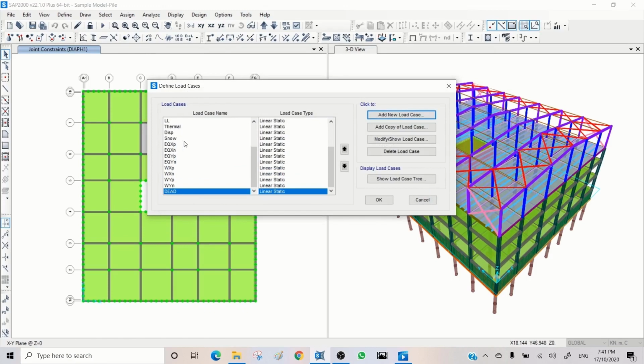So anything else we can add? We have just one type of live load, which is okay. Soil, I prefer to keep it separately, and the rest can be separated. You can combine wind and earthquake loads, it's up to you, but I want to see them in my load combinations. I think it would be easier.